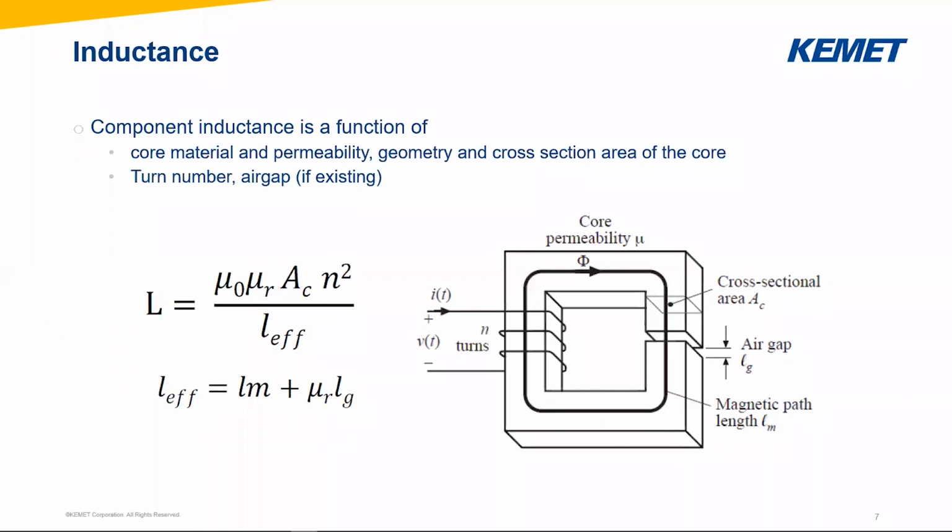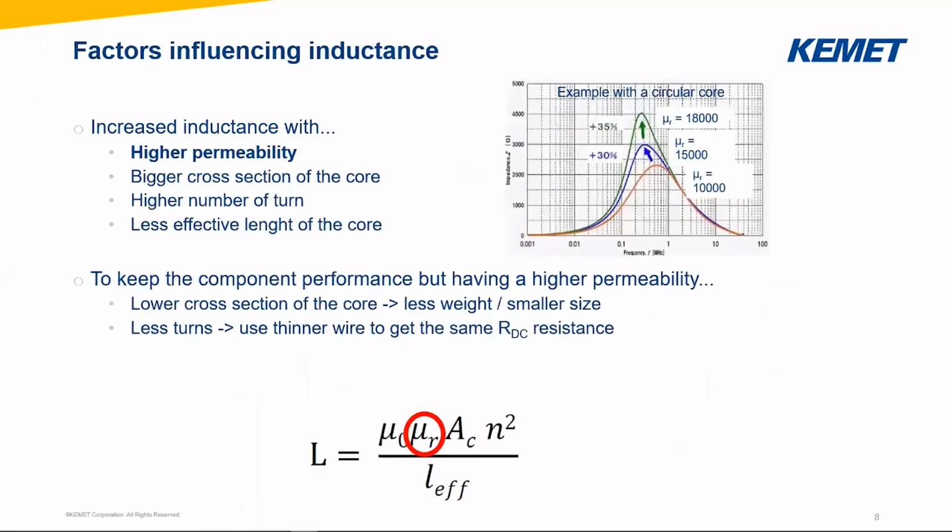Well, now, I could think about increasing the magnetic permeability to some high values, but there's some behavior. And here we can see directly the behavior of the μr. The orange curve is the μr of a material with 10,000 μr. But the more we increase the μr, the more we change the frequency range to a lower frequency.